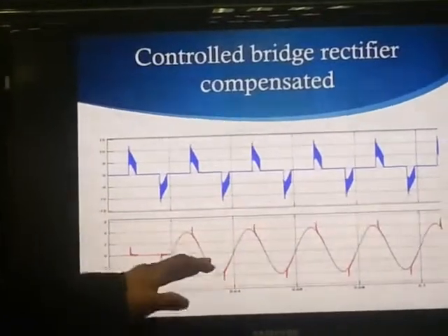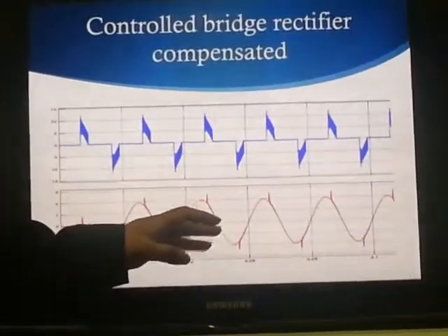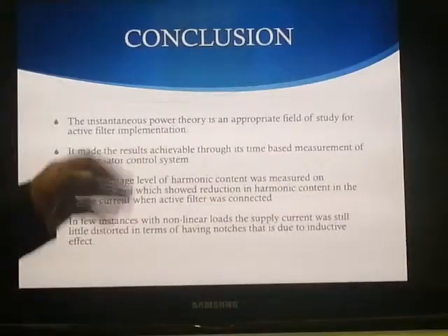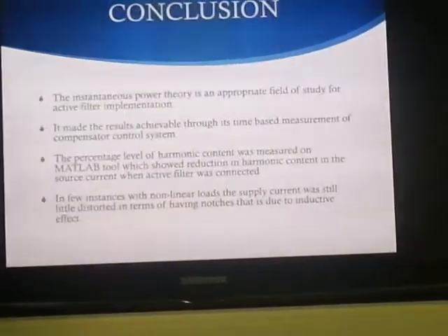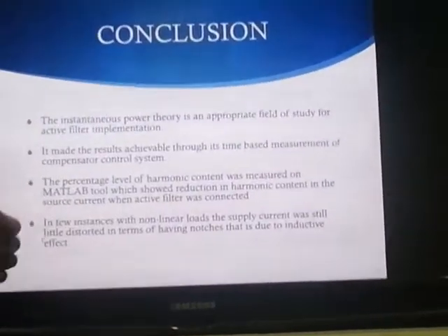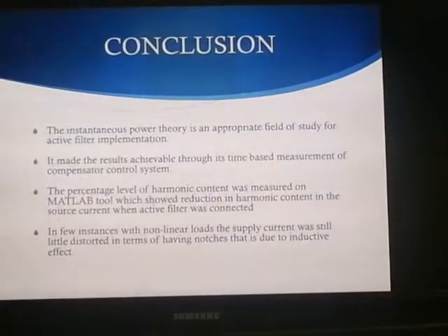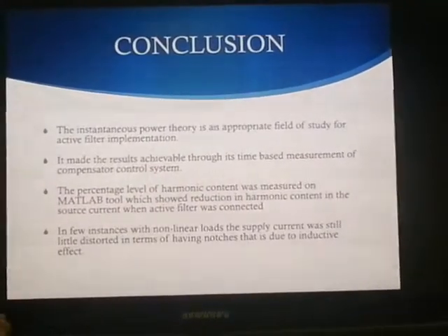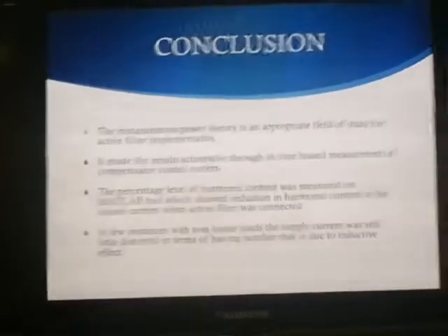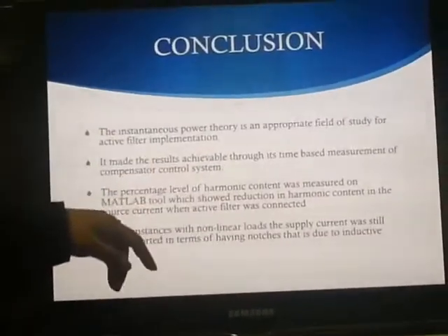But, however, the supply current is still very much sinusoidal. We were able to remove most of those high harmonics. In conclusion, I wish to mention that the instantaneous power theory is an appropriate field of study for active filter implementation. It has made the results achievable through a time-based measurement compensator control system.